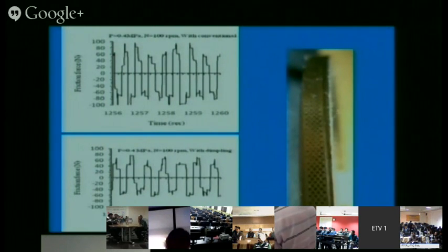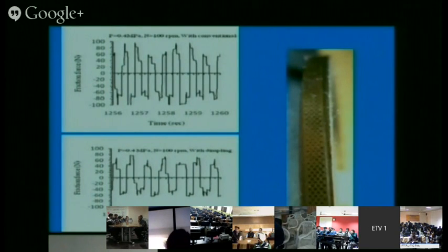As I discussed, only the top compression ring had its profile modified. We measured the total friction of the ring pack, because there are 4 rings in total, but we modified the profile of only 1 out of 4. Roughly 90 or 100 Newton friction force comes when the complete ring pack is there without modification of the profile.